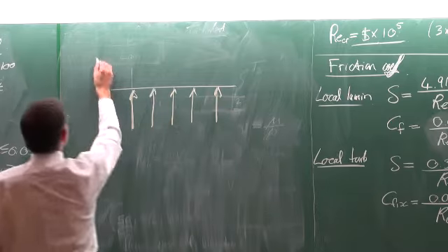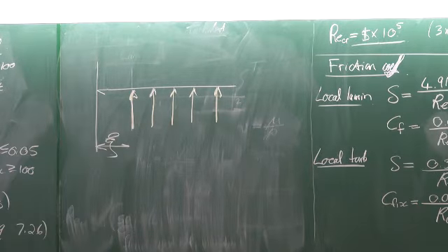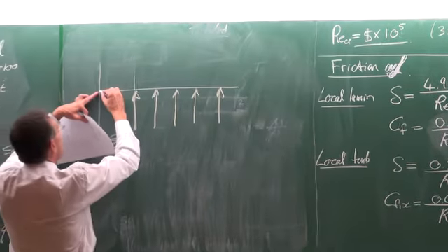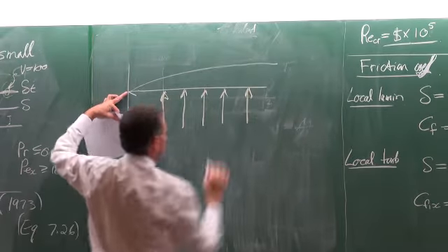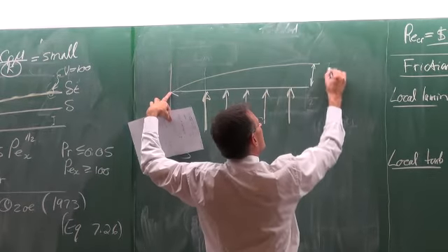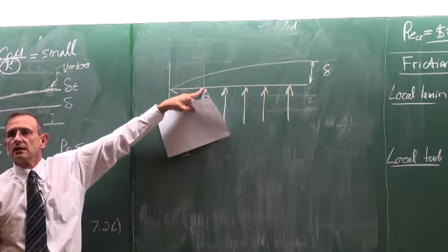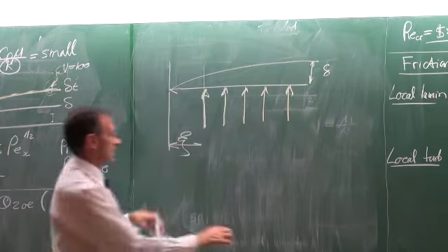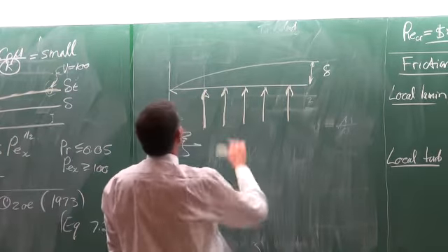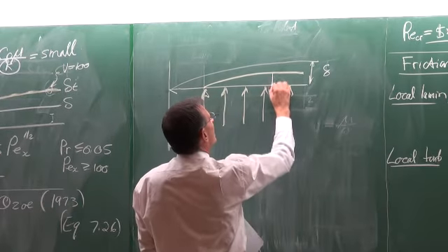Here's a distance here where there's no heating, and what now happens is that the velocity boundary layer starts developing there. But the heating only starts here. So the thermal boundary layer would now start developing here. So like that.